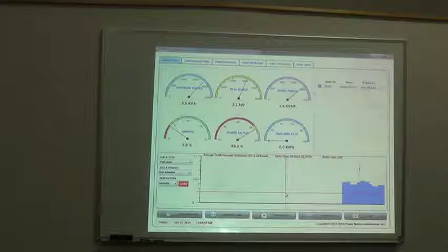If the harmonics go up by more than 50%, I shut down the unit because I don't want to be causing harmonics. Unfortunately, let's say you require 140 microfarad. We don't turn on all the 140 microfarad at once, because that will shock the system. We basically do 40, 80, 120, until we get up to the right value, because as you apply capacitance, the system changes.